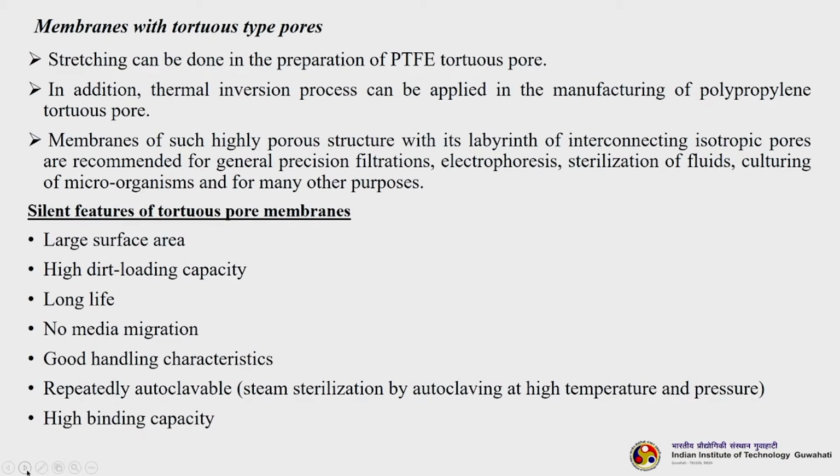Stretching can be done in the preparation of PTFE tortuous pore. In addition, the thermal inversion process can be applied in the manufacturing of polypropylene tortuous pore. Membranes of such a highly porous structure with its labyrinth of interconnecting isotropic pores are recommended for general precision filtrations, electrophoresis, sterilization of fluids, culturing of microorganisms and for many other purposes.